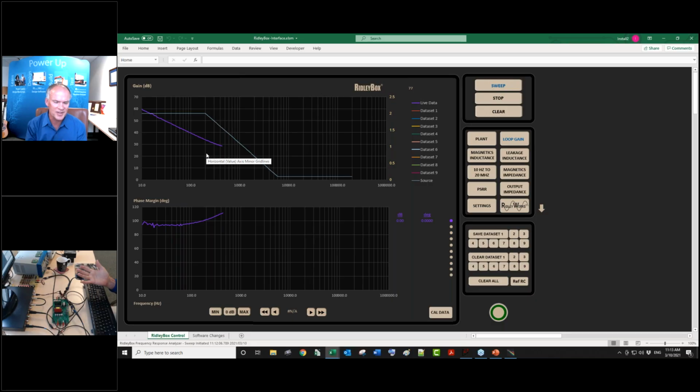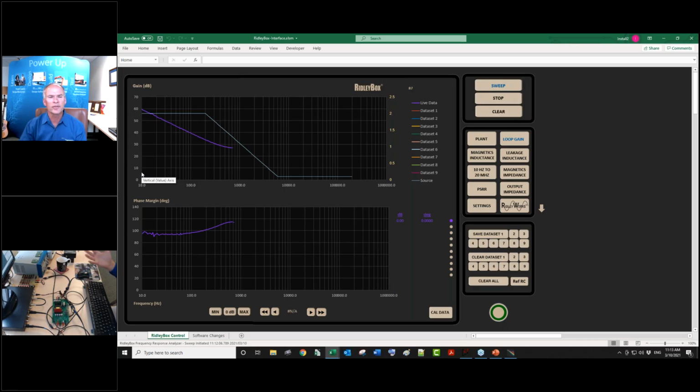What good is a scope if AC coupling won't measure 60 Hertz? Okay, it's not going to help you very much. So always 10 Hertz is where you start these things up. And the old HPs, of course, that's as low as they went. If you're doing power factor correction measurement, then that start frequency has to be about 0.1 Hertz, which is why we designed our transformer down there. Because you want to see all the gain, you want to make sure the compensator is doing its thing.